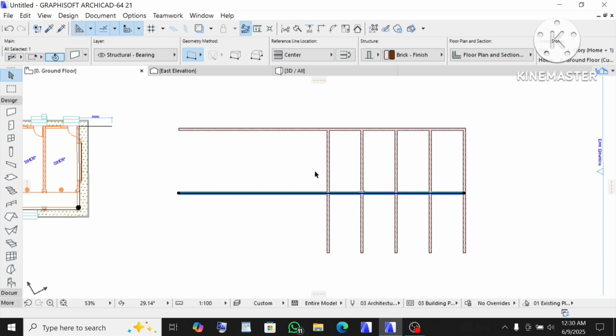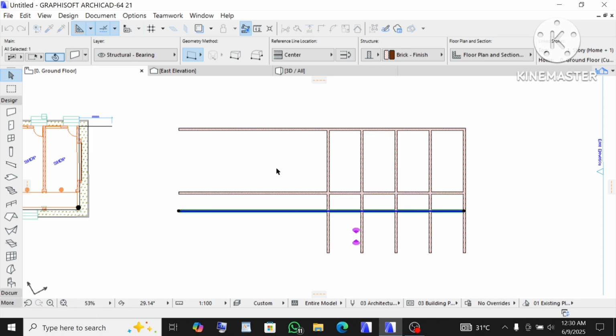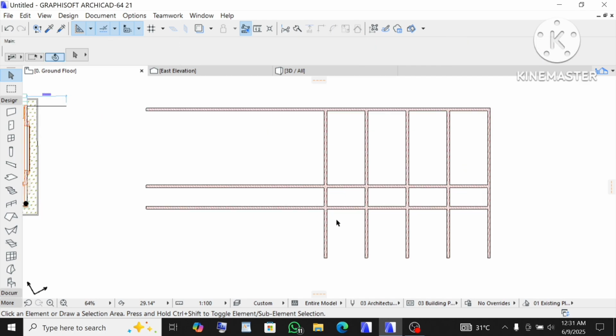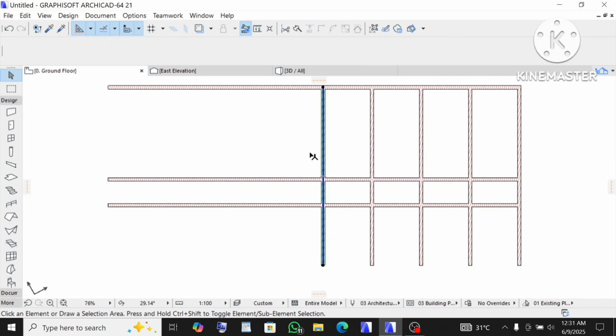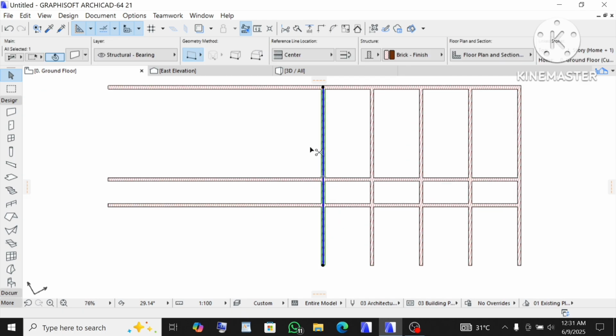You see that. And I'll also press Ctrl Shift D and click, take it down by that 1.5. Wall thickness 225, so everything would be 1725, and press Enter. You see that. Now I will click this wall and offset to the left by 1.5. Ctrl Shift D, hold it on your keyboard and leave. Click, take it to the left by 1725, wall inclusive, then press Enter.